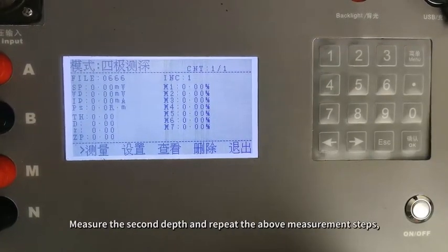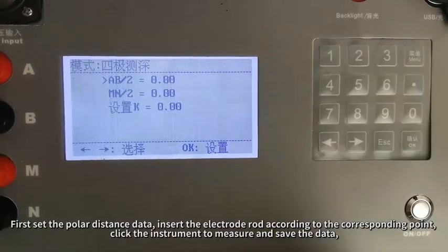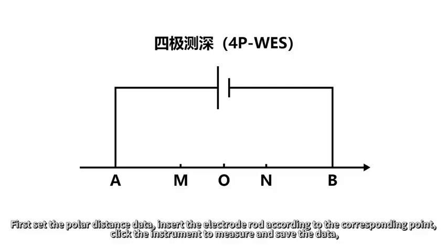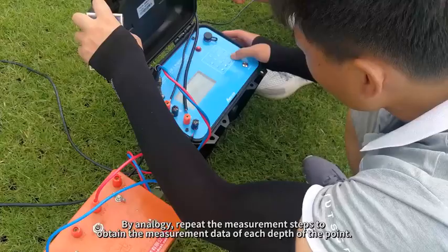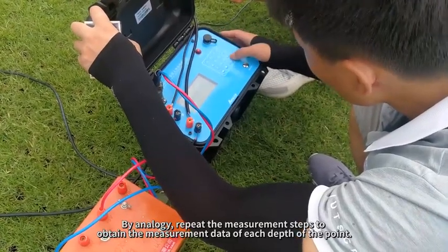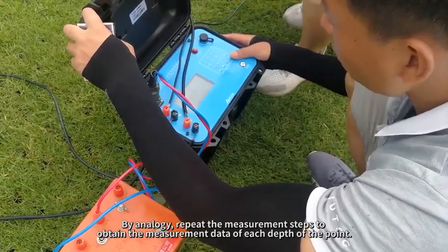Measure the second depth and repeat the above measurement steps. First, set the polar distance data. Insert the electrode rods according to the corresponding points. Click the instrument to measure and save the data. By analogy, repeat the measurement steps to obtain the measurement data of each depth of the point.